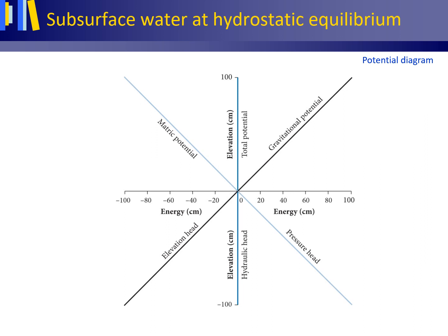Because the matrix potential or pressure headline remains locked in its present position, choice of a reference level does not influence the shape of a total potential or hydraulic headline or curve. One may therefore always simply choose the reference level that comes in most handy. Of course, once a level is selected for describing the energy levels at a specific location, one should stick to it. In fact, as the water table moves up and down, in practice it is better to take the land surface as reference level for the elevation head and gravitational potential.